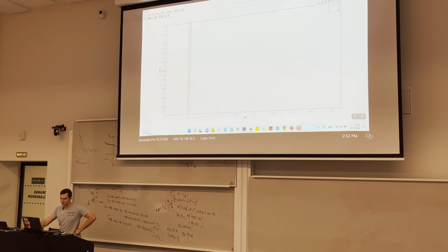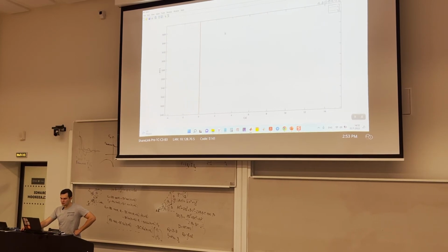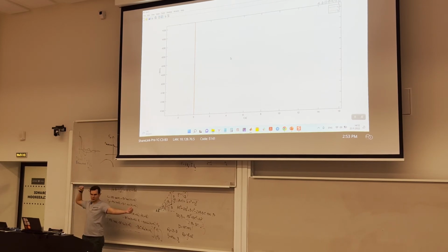Yeah, there is no such a driver that can produce such amount of torques. It just does whatever we ask it to do. I mean, the initial position was like this, and the trajectory right here. And the robot with a certain amount of gravity went here, and it took less than 0.2 seconds. So it needs a lot of energy to go there, and it's pretty unrealistic. This is why I used saturation.